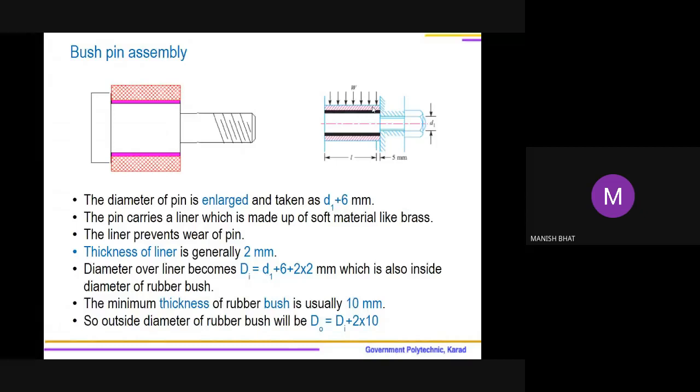So drive is transmitted via the bush. See here, there is no permanent joint in between. We have learned earlier, see, the bush is touching the other flange. So how is drive transmitted? Are you observing here? In this 5 mm clearance also, the bush is seen.